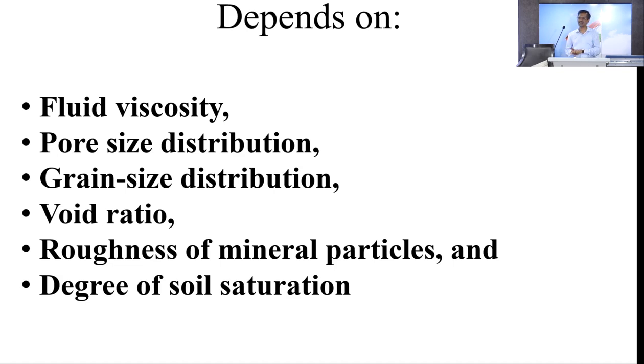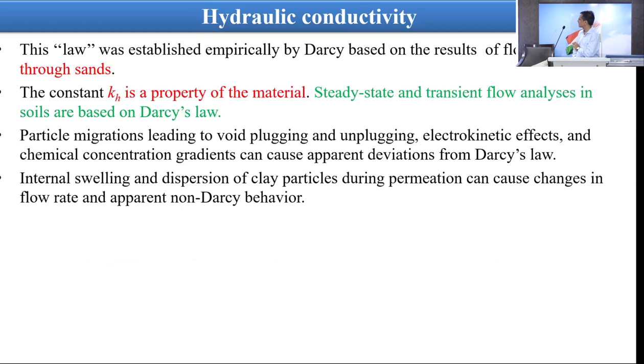Similarly, pore size distribution. Void ratio is not the only factor; even if the void ratio is the same, how the pores are oriented matters. The people in the petroleum industry do lots of work on this, whether there is a crack or so, and then the flow will be more than the available void ratio. Grain size distribution, roughness of the mineral, and degree of saturation. These are some of the aspects which the flow depends upon.